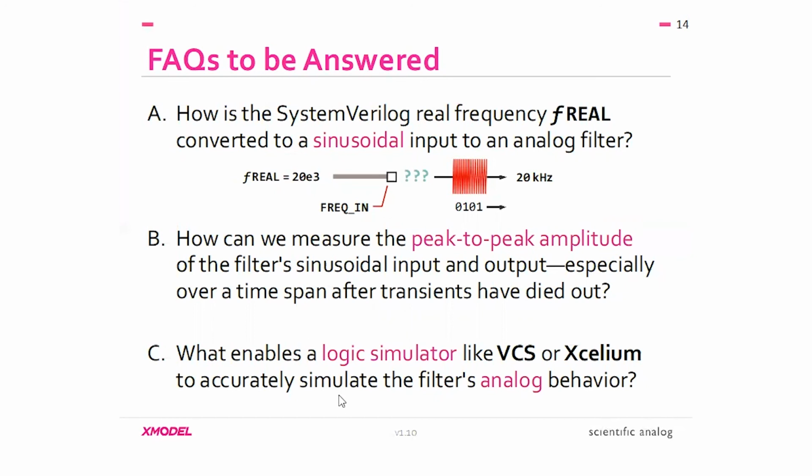And finally, what enables a logic simulator like VCS or Questa or Excellium to quickly and accurately simulate analog behavior? Well, we've already mentioned the data types XReal and XBit, and we'll see those in more detail in the sections ahead.